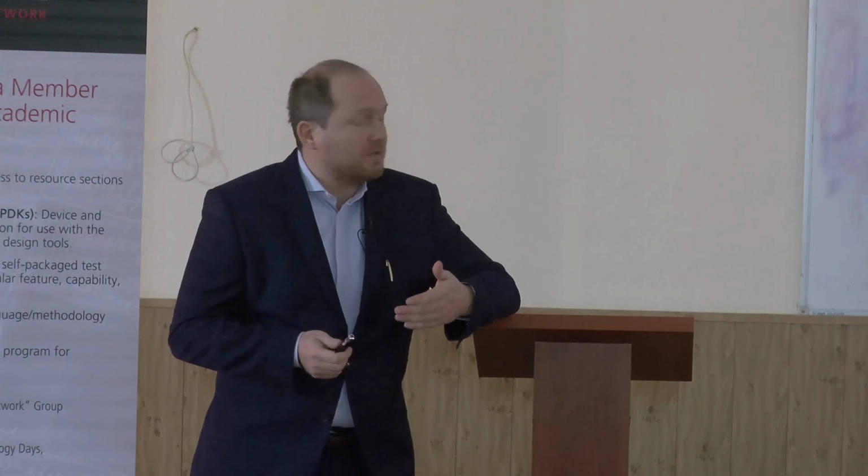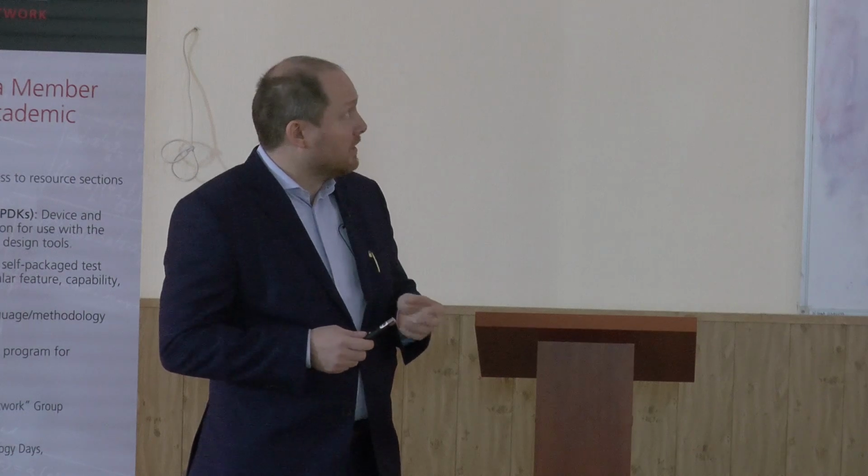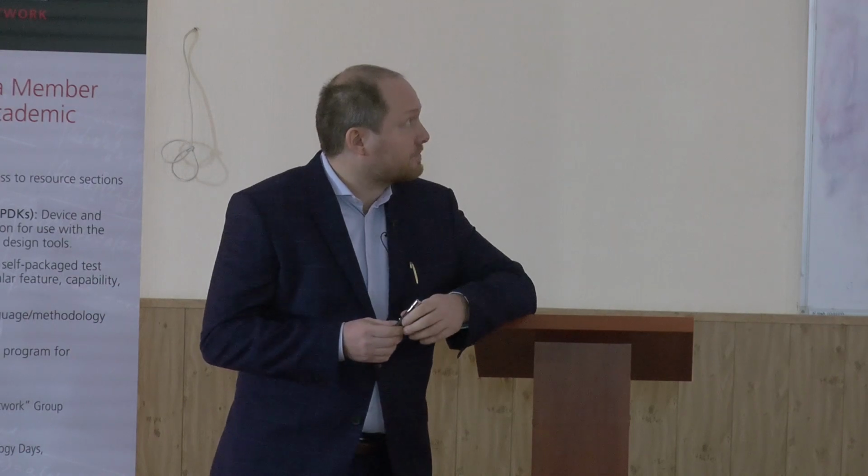Also, if you integrate ECUs on one system on a chip, then it's a higher security, higher reliability, and also security of supply, because you just have more chips produced which you can integrate in different cars. Also, if you want to have very advanced features like ADAS, assisted driving, then you have no choice but to integrate it into an SoC because of the amount of data which you cannot transfer on a PCB. So all the data transfer consumption must happen on an integrated chip.